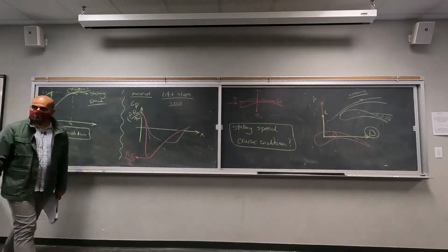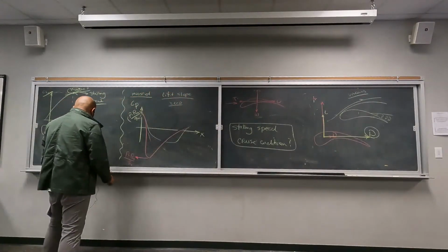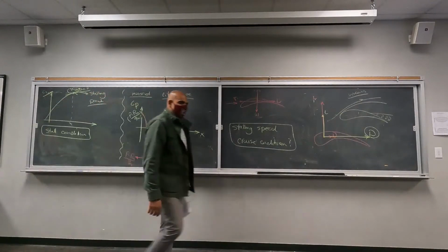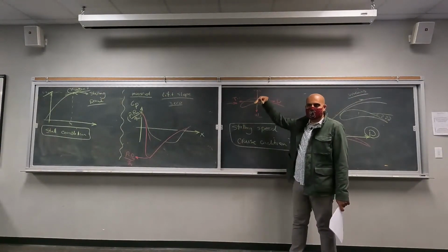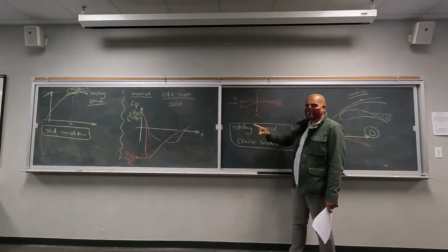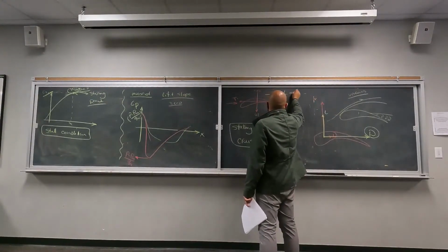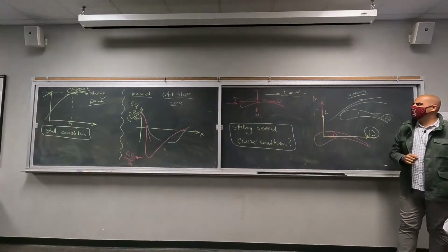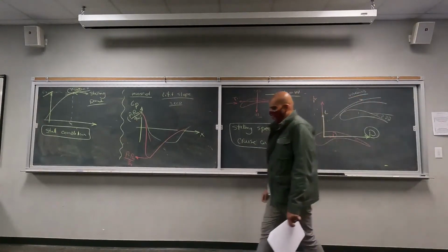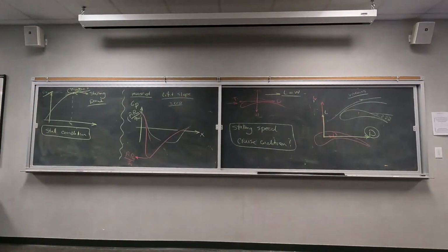Lift equals weight, right? Because you don't want to have any excess in any direction, in the y direction. If your weight is higher than lift, then your elevation will decrease. If your lift is higher than weight, then you will start pitching up, right? That's the idea. So for cruise condition, lift has to be equal to weight. Okay, so that's one statement we can say about the cruise condition.